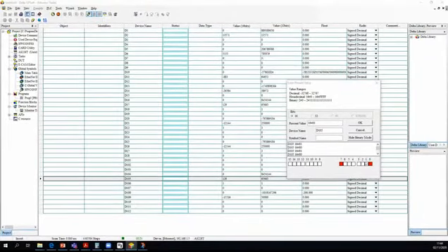I can also set the drive to move in absolute positioning. So instead of incrementing by 50,000 every time, I can just set it to move to the absolute position, 50,000. Right now it's at 250,000. So if I enable this bit and trigger a new position command, you should see that it is not happening, because I have not done a homing on this drive.